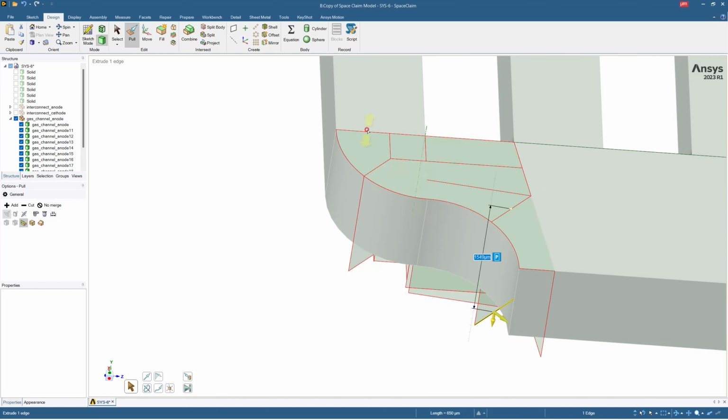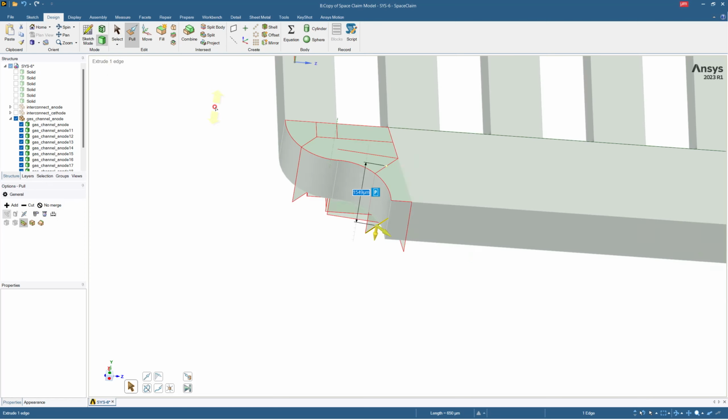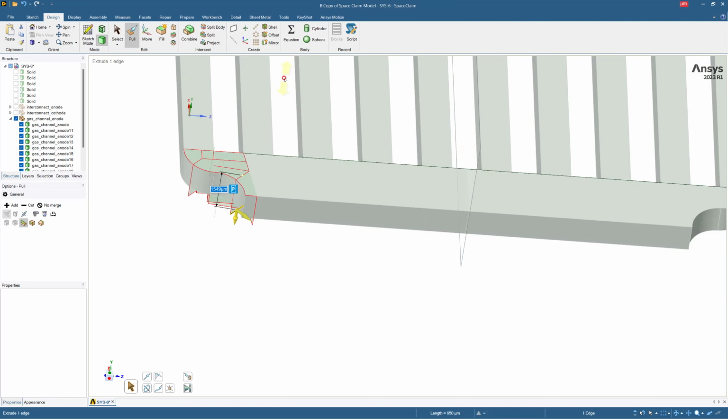So let's begin by dividing only this body into different bodies. So we will continue by making it. First we'll want to divide it with this mirror image also. So we'll split the body, select this body, and by the central image, and delete this part because we will mirror it afterwards.